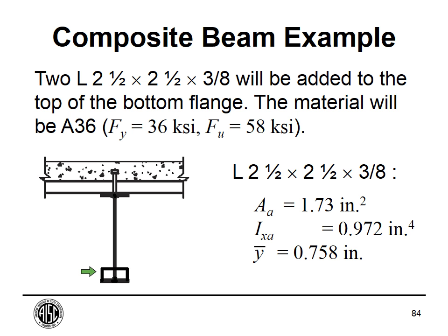And just to make things more interesting, I said let's use A36 because we're going to combine with the beam, which is 50. I wanted to make sure we knew how to do that. The reason I chose 2.5 for the horizontal dimension is so that I could get a good weld, so that I could get a good shelf between this leg of the angle and the edge of the tip of the beam flange.